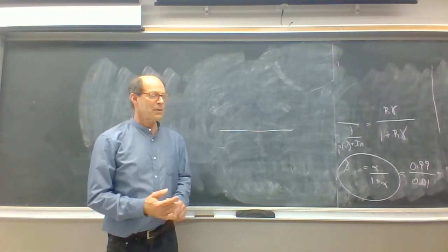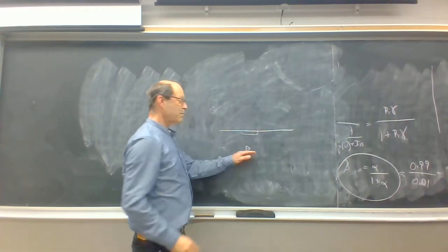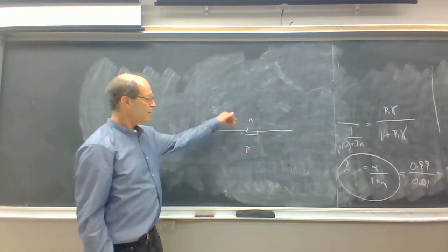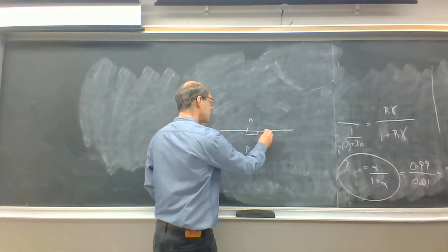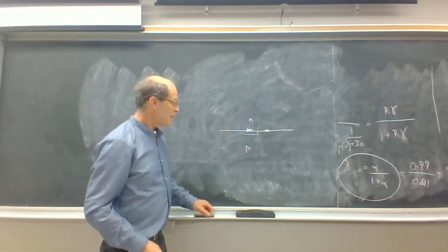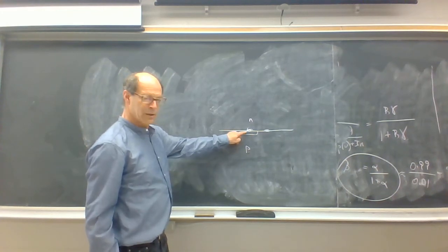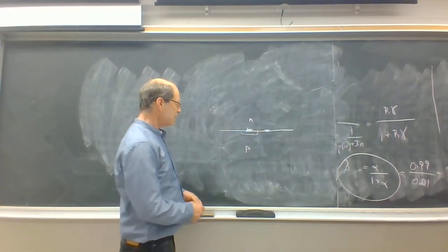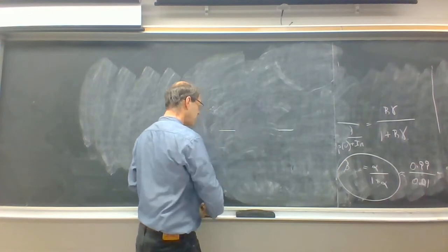And we described the PN junction as a device where you would, for example, take a p-type silicon substrate and create an n-type region in the substrate by a diffusion process, and that n-type region would form a PN junction by putting ohmic contacts on the 2 different semiconductor regions. Of course, you could also reverse this, and you could create a p-type region in an n-type substrate. Well, it doesn't take much imagination to extend this into the formation of a bipolar junction transistor.